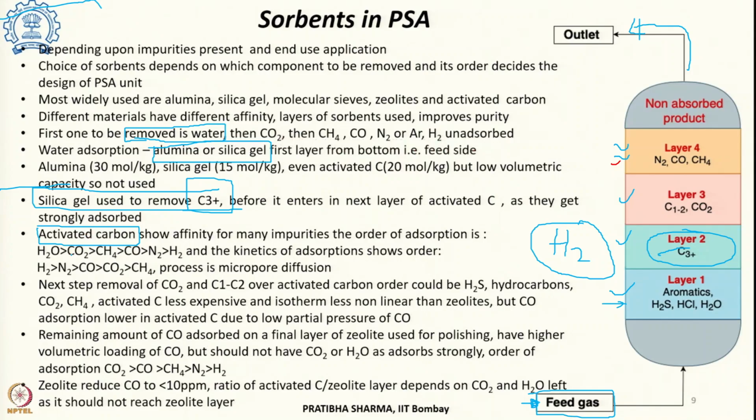This activated carbon will also adsorb carbon dioxide and CH4. Okay, and next step, what is the next step? Next is the carbon dioxide removal step. Okay, next step is the carbon dioxide removal step, and C1, C2, I mean CH4 also will be adsorbed.